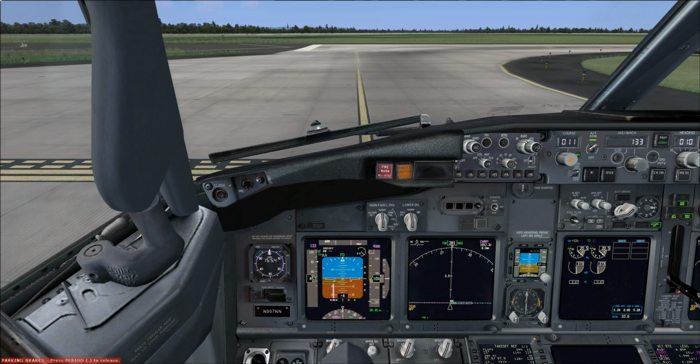Now when he gets into the downdraft, remember, this downdraft is rushing down towards the ground, but as he gets into the downdraft, he already has the power all the way back. The nose is down, trying to lose the height that he gained. So the aircraft is already in a low power situation, trying to descend, and it gets pushed down further by the downdraft. So obviously you can see where that would go. It could turn out to be pretty bad.